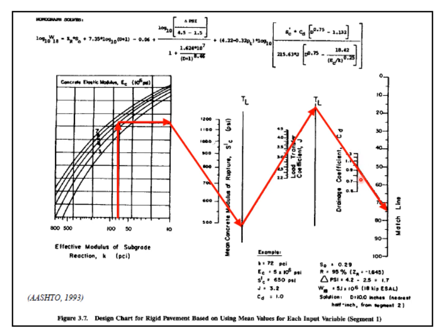Let's say the drainage coefficient value is this one. So starting from here and considering the value of the drainage coefficient, just draw this line and reach here. This is again the line which is considered as the match line, and if you just look at that, it is nearly equal to 74. Now the next part of the nomograph is present on the next slide.